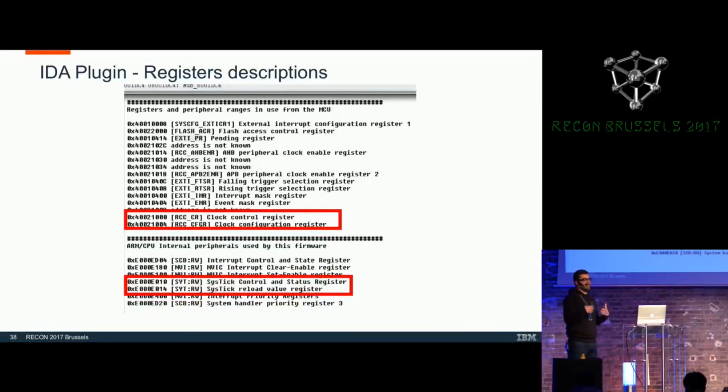So if by chance, because some of these addresses can be generated at runtime, you cannot find the specific register where the GPIO is being written, you can just search for this kind of register, which will tell you exactly which GPIO buses are being used. Some of these addresses can be hard-coded or generated in memory. However, the compiler tends to keep some of them hard-coded so that it doesn't need to make so many operations during execution.